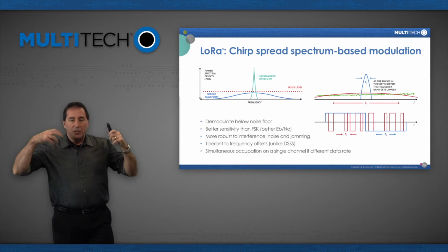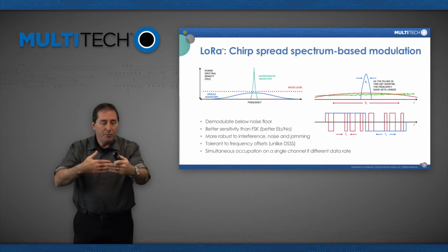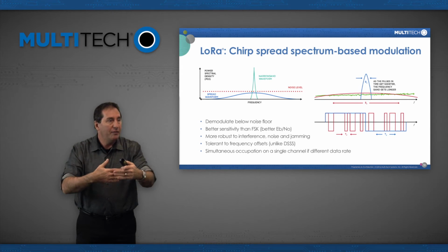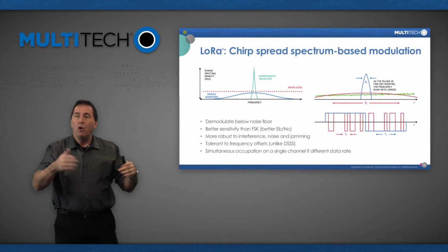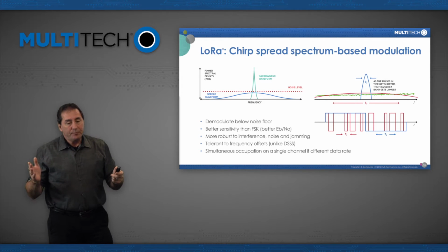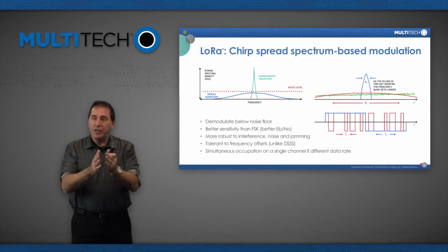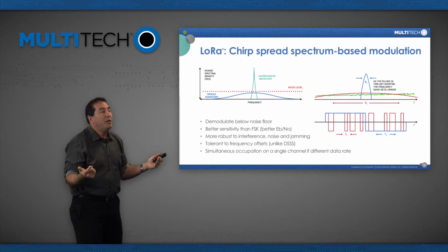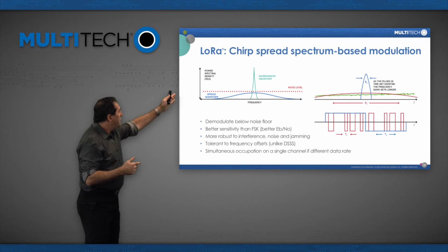You basically just start talking and you add some stuff on the front that allows a receiver to lock on and connect to you. So you don't have to be always locked onto each other. And then the spread spectrum is, when you take a signal, there's a couple of ways that you're going to see in industry that they use radios. And one is this narrowband.